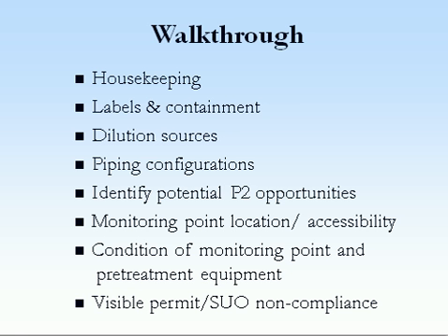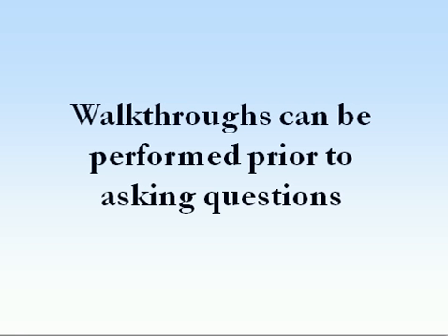You want to make sure that you're able to get in there and use that monitoring point. And the condition of the monitoring point: is the tubing going to your sampler clean? The industries need to maintain those places and make sure that everything is usable and that they get a representative sample.